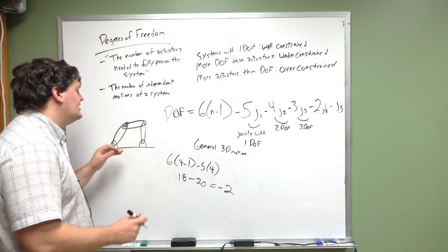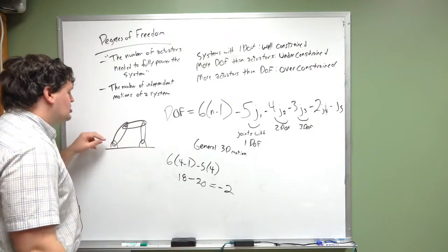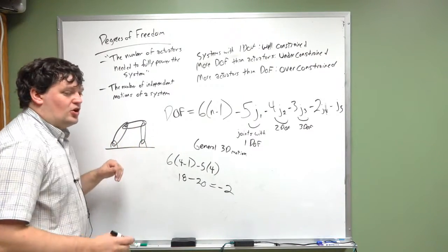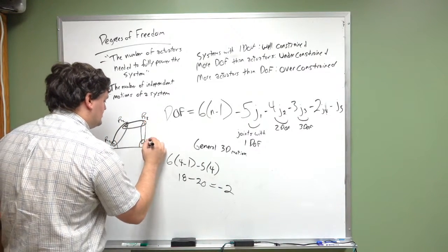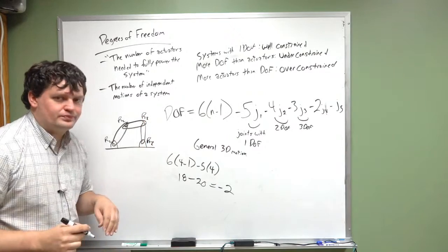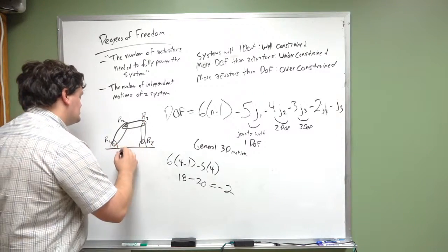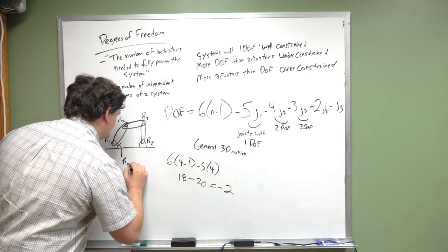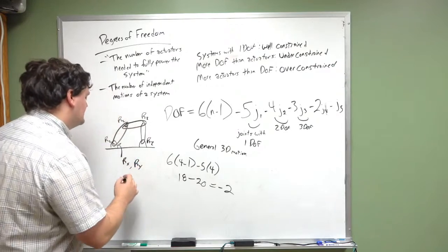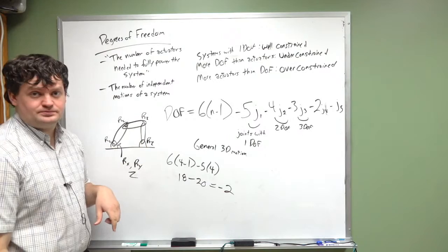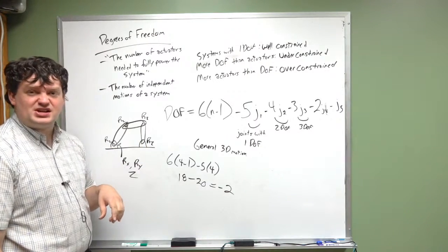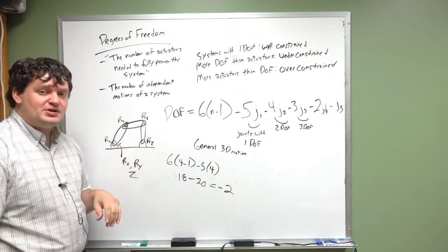One of the ways to do that is with this system, you have 2 different joints. All of these joints only allow rotation in the z direction, which is great, but that means you're carrying Rx, Ry loads, and Z loads through both pins, which is kind of unnecessary. You only need 1 pin to carry it.